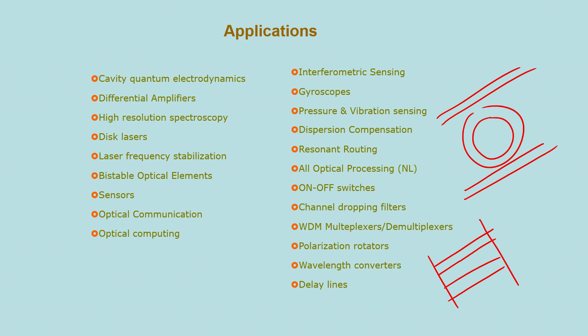One of the important applications is called the delay lines. It is very difficult to achieve delay on the chip because you have very small length. If you use gratings you have a good amount of delay, and the ring resonator is another important way to obtain a good delay line. This has applications in communications to correlate different signals, the recognition of the optical header in a communication link and so on and so forth.